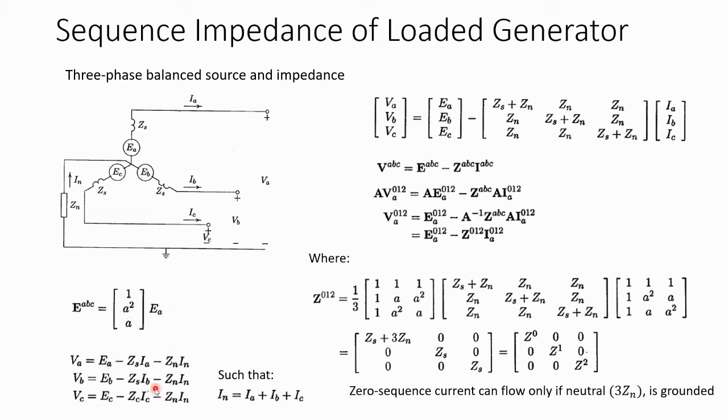And then we can also derive this equation, which is a simple voltage drop for phase A, B, and C. So take for example, in the derivation of this equation, we will walk through this circuit from here to here. As we arrive here, we will have a voltage drop of negative IA ZS, and then we get positive EA, and then we get negative IN ZN, and then we get negative VA equals to 0, and we form a complete voltage drop. And then we rearrange the equations, we will obtain this form. And we can apply the same concept on phase B and phase C as well.